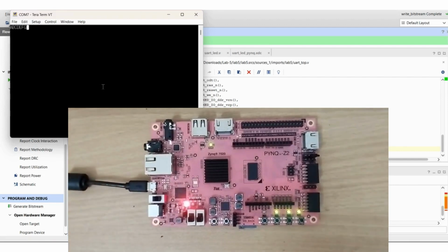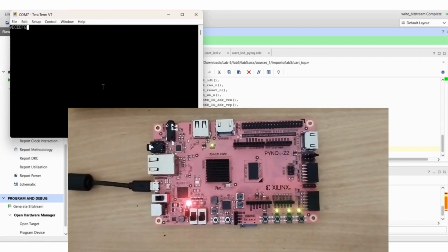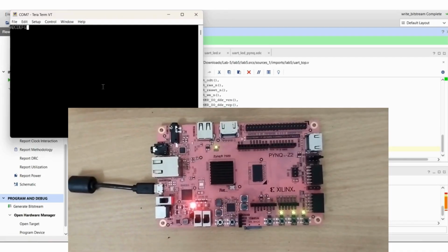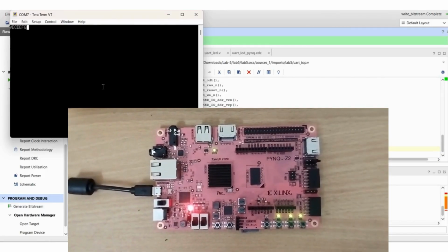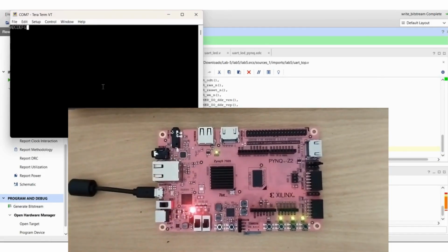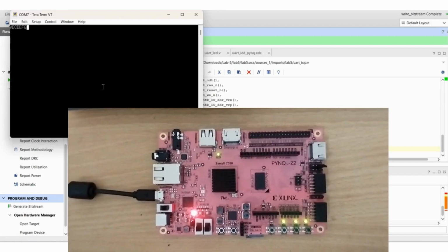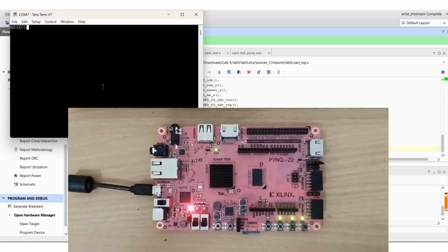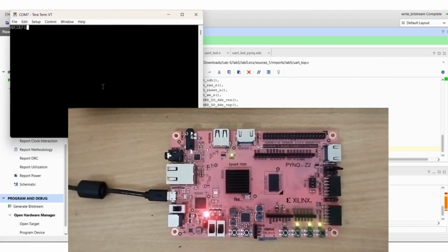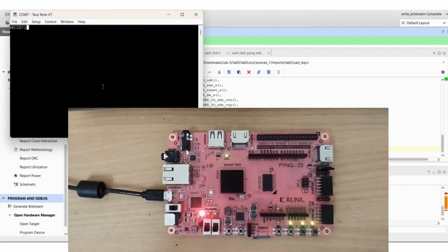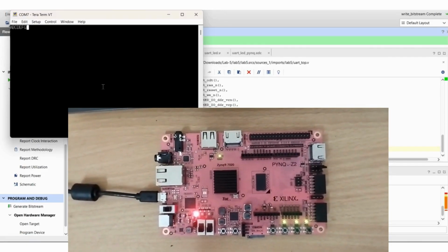This design also includes an interactive feature using a push button that I have already demonstrated. When I press the button, it will swap the lower nibble with the upper nibble. In summary, UART input sends ASCII characters, LEDs display the binary equivalent, and only the lower 4 bits are visible. If we have to see the upper 4 bits of the binary representation, we can use the push button to get the upper nibble. So this experiment demonstrates how digital systems process, manipulate and display data in real time using FPGA hardware. I hope you understand the complete process. Thank you.